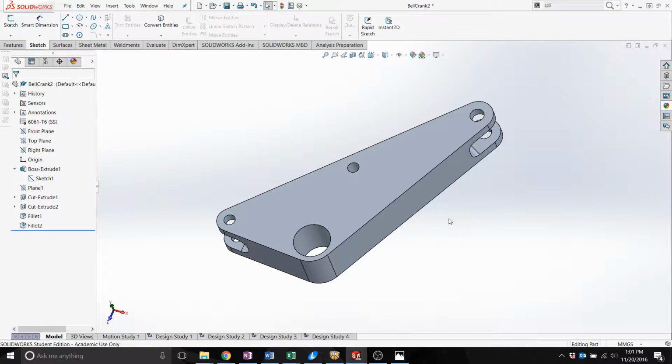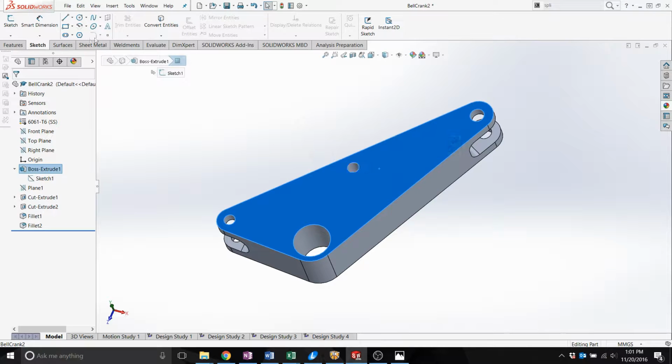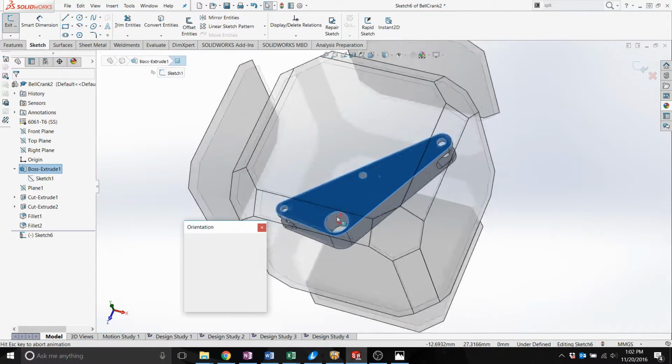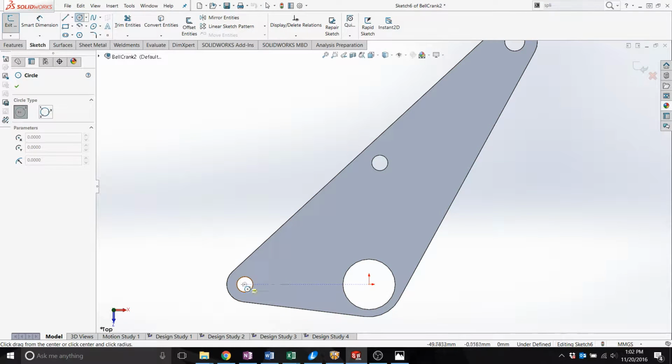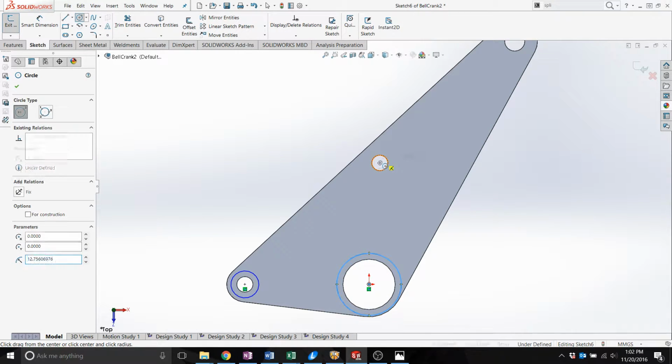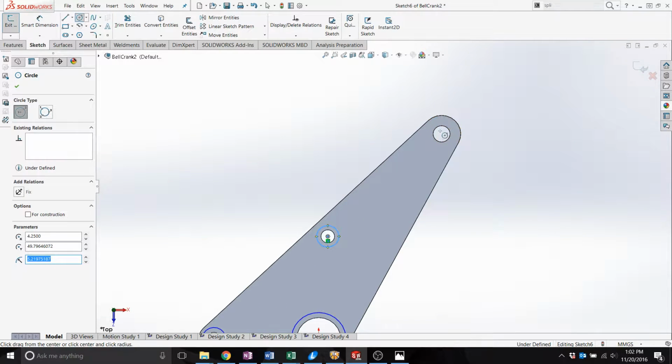So with that, we're going to be using the split function to effectively split this volume into a bunch of different volumes. And to use that, you need to have a sketch on this face to start. So we're just going to be creating a few circles around our constraint spaces. These diameters aren't very critical.